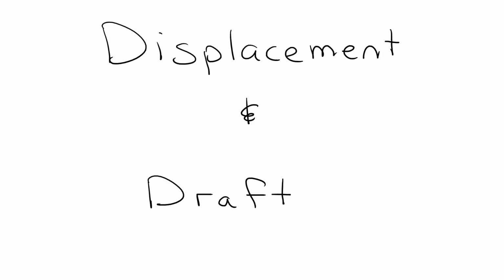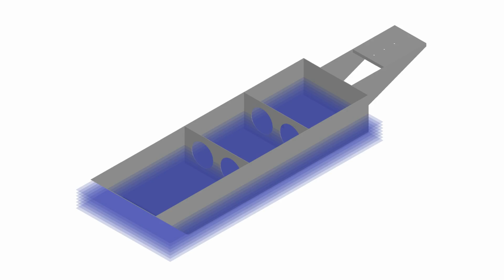The first thing we're going to do is calculate the volumetric displacement from our water plane areas. On my example boat, I have some water planes listed, and where they intersect the hull, we're going to get water plane areas. It's important to note that we are not going to calculate the water plane areas of the cantilevered steering assembly, and that's because this is not a watertight assembly, and therefore the amount of water it displaces is negligible compared to the amount of water that the hull displaces.